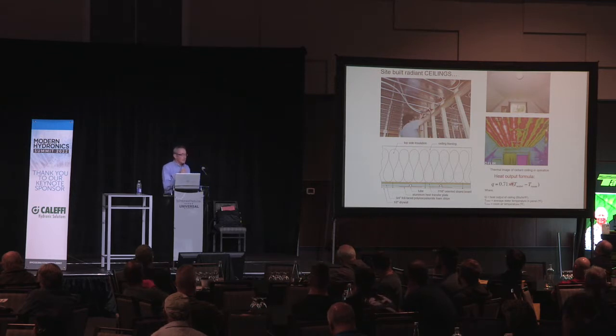And think about this, if we could get 28 BTUs per hour per square foot from a radiant ceiling, but our design heating load in the building was only 10 BTUs per hour per square foot, the implication is 1 square foot of ceiling would cover the load of 2.8 square feet of floor area. So we don't necessarily have to do the entire ceiling with radiant panel construction. It might be part of the ceiling, okay? So again, that's a cost-saving option for you.